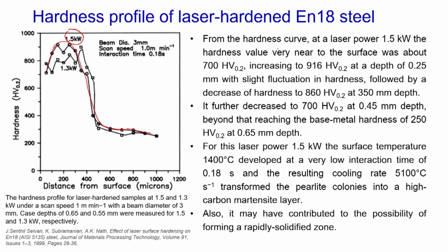For the hardness curve at laser power of 1500 watt, the hardness value near to the surface was about 700 HV. The maximum value was noticed about 916 HV at the depth of about 0.25 mm, about 250 microns, with slight fluctuation in the hardness.